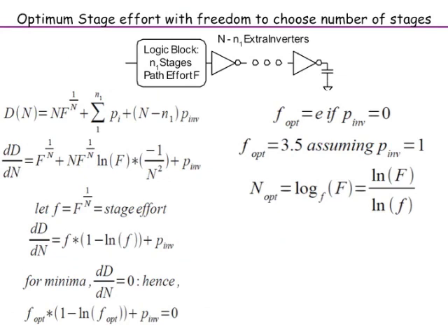Now these design tools, like optimization programs or synthesis tools, do this multi-input multi-output optimization simultaneously. All paths are being optimized at the same time. But the idea here is that there are certain simple paths, certain simple symmetries, which you can handle by these kinds of approaches. Like decoders, for example, have a very nice symmetry, branching, and so on. So again, you can optimize using this concept of logical effort and this kind of analysis.